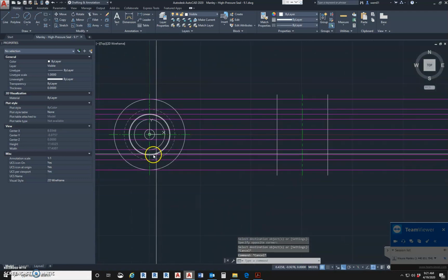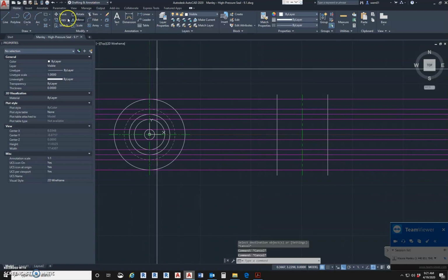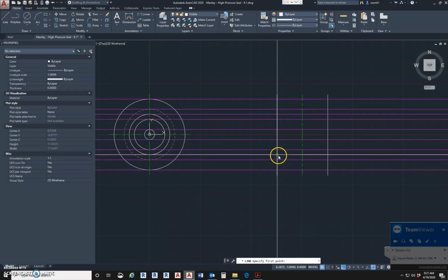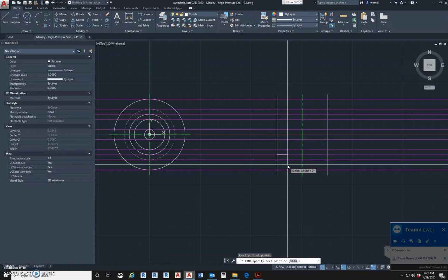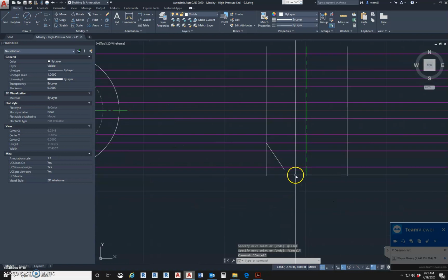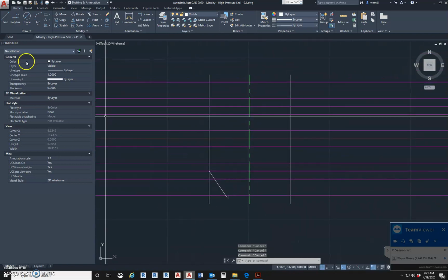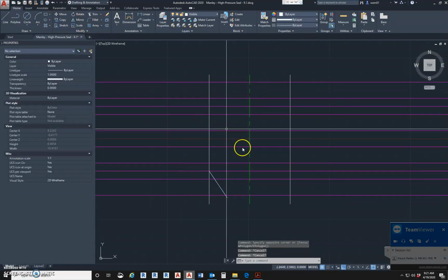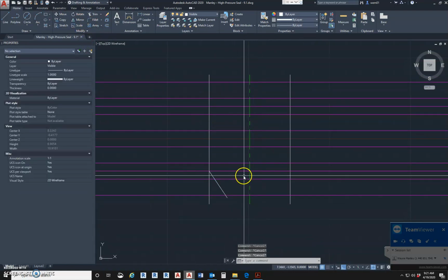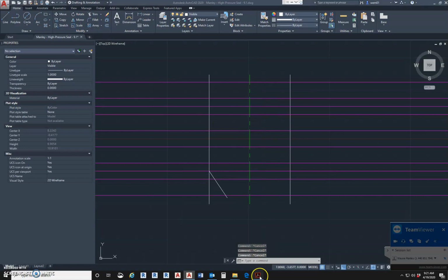So we knew it was the center line, correct? So I'm going to go to line, go to this point where it matches, and then I want to type in at. I want to do the 1 for the distance, and the angle is 304. There you go. Now we don't have to keep typing that because we have the benefit of having the mirror command.